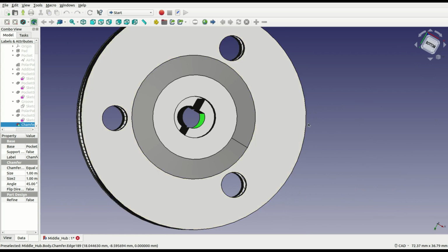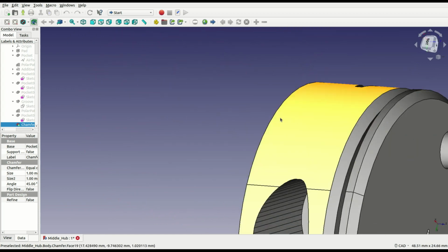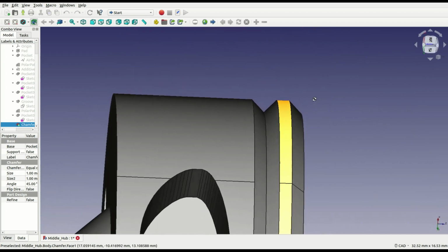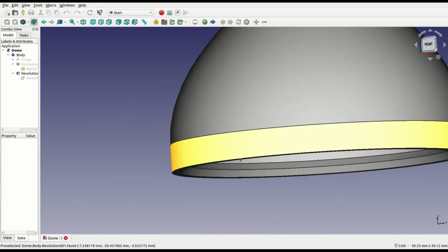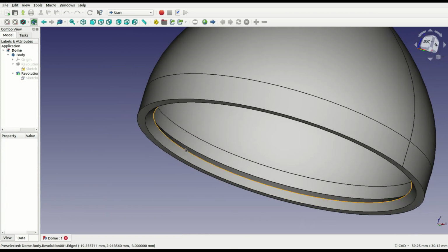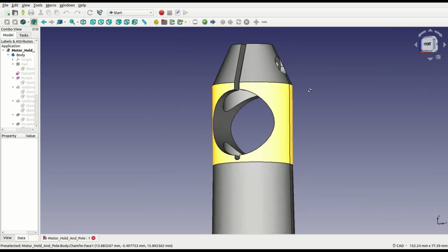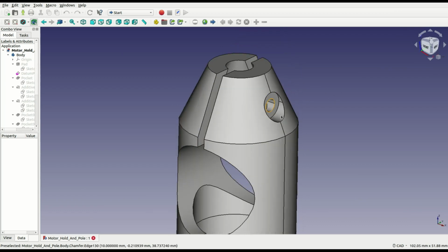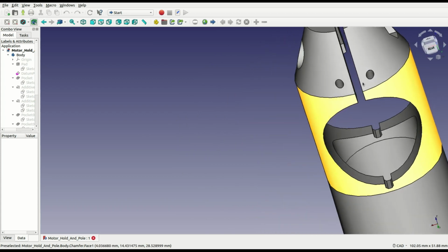I also thought for quite a while how to connect the dome to the hub, until I thought of this groove. It's a bit difficult to put the dome in place, but once it's in, it moves around really smoothly. Here's the dome. You can see the counter groove here. And finally, the wind turbine stand, which holds the DC motor. The bore is the exact diameter of the motor, and I used an M3 screw to tighten it in place. And here are the holes to allow the resistor and LED to pass through.